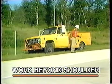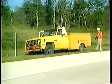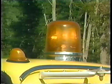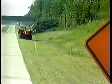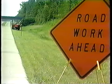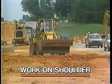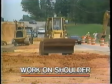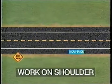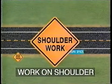In the first example, the work is entirely beyond the shoulder or parking lane. Traffic control will generally consist of flashing vehicle lights and flags. An advance warning sign should be used when the work will interfere with traffic in any way. Now, let's look at work on the shoulder or parking lane. If there is no direct interference with traffic, the motorist should be warned with the sign "Shoulder Work," as shown.